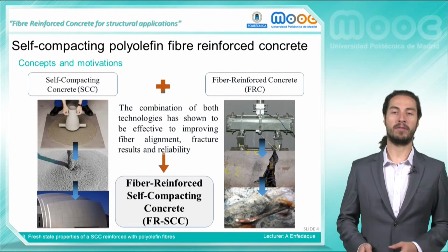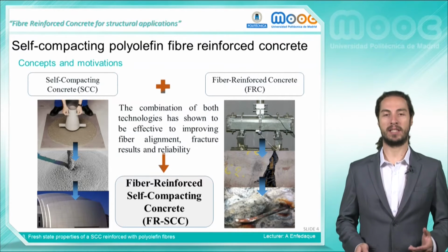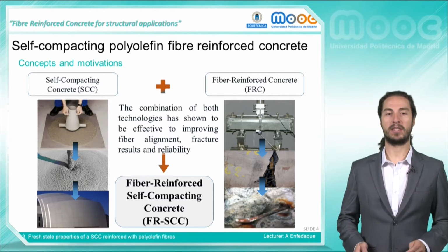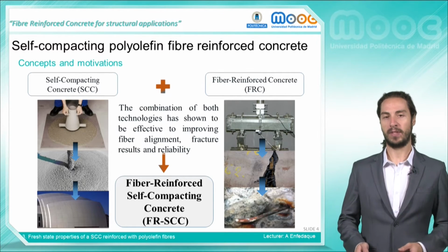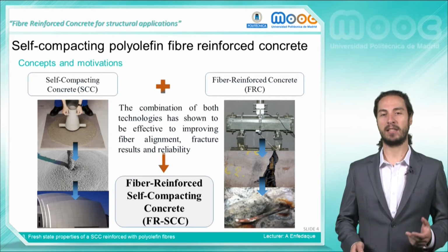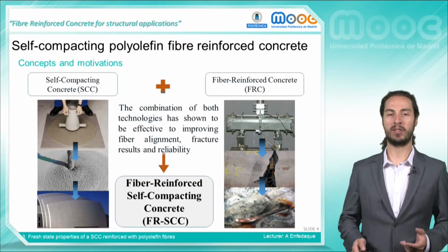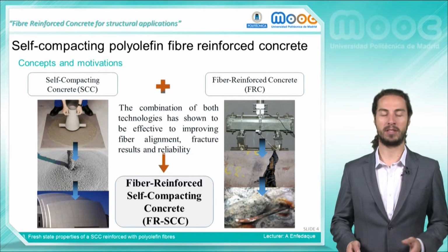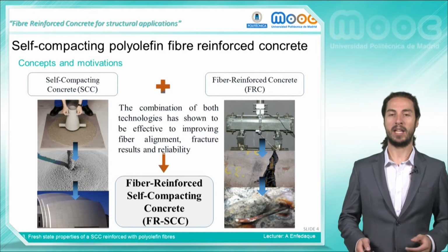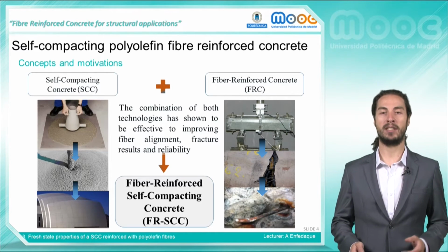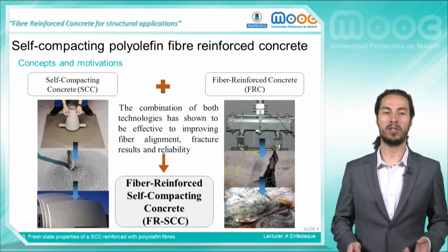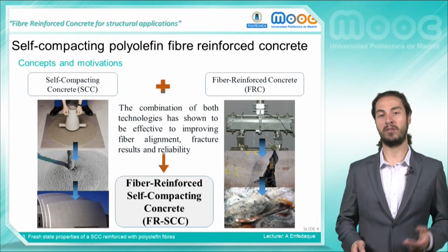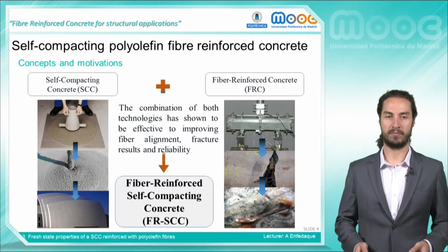First of all, self-compacting concrete, also known as SCC. This type of concrete shows its main property when it's poured. It behaves like a liquid and not as a semi-solid. This property provides high benefits, including the enhancement of productivity and reduction of the overall cost of the structure. In addition, its fluid state enables the possibility of reaching congested reinforcement areas, having an excellent mechanical response with great durability and uniformity of the material obtained.